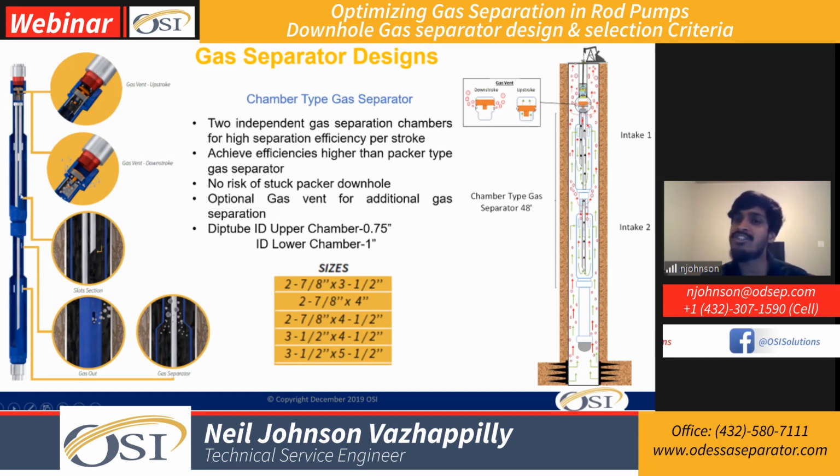The overall pressure drop inside the dip tube is much higher if the fluid goes through the longer one compared to the shorter dip tube. That is exactly why we needed to calculate what can give a close to even distribution in both of these chambers.